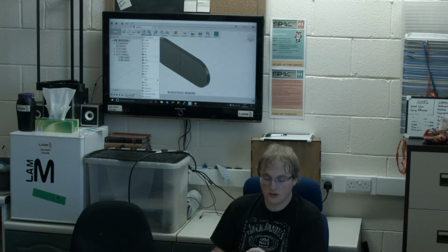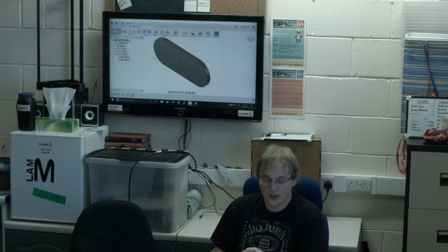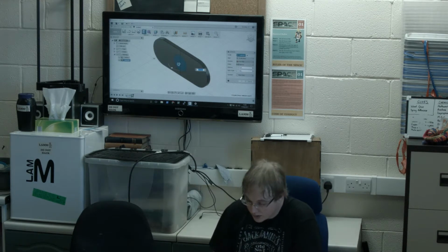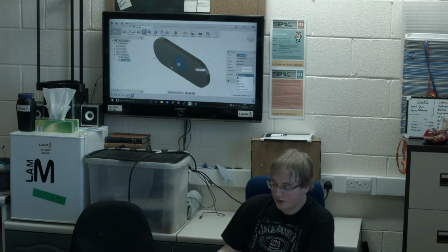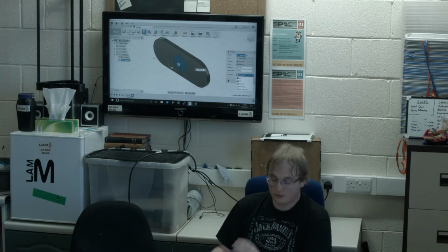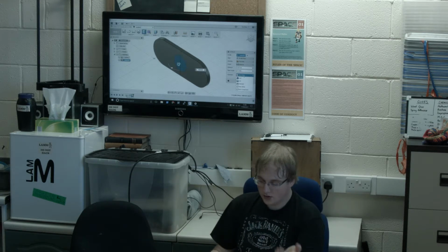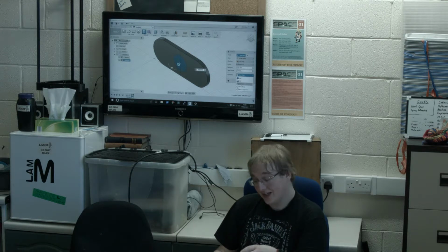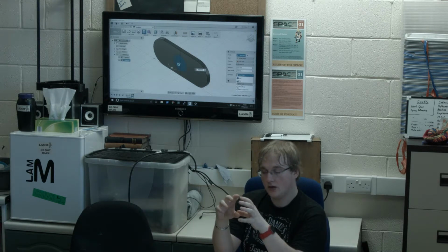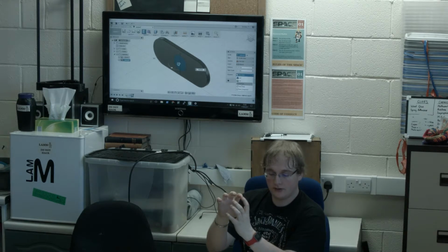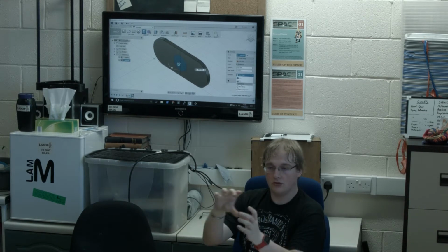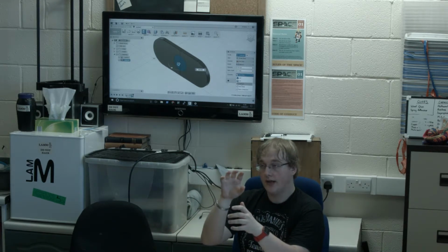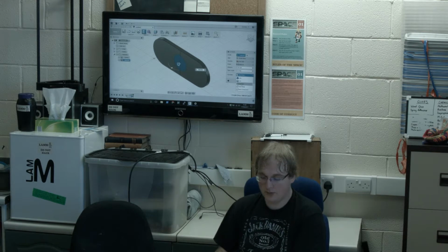For that, there's no extra different cut tool or anything like that. It's extrude again, but this time you look at the operation. You can either put in a new body, where you extrude it out and create a new item, or join it, so it will always be there, or cut it, which is what we'll be doing, or intersect. If you push it inside, anything that is intersecting stays. Say this was a different shape and you were cutting a circle through it to get extra contours out of a particular part, then that would just leave that piece there.